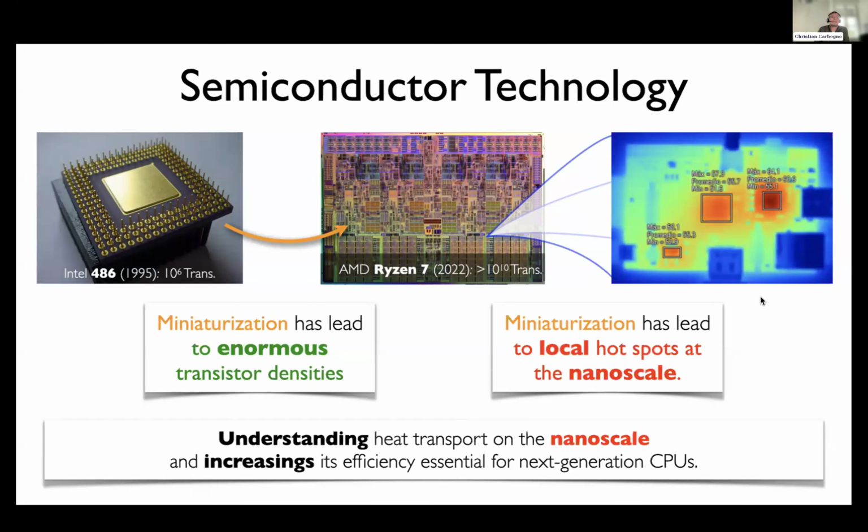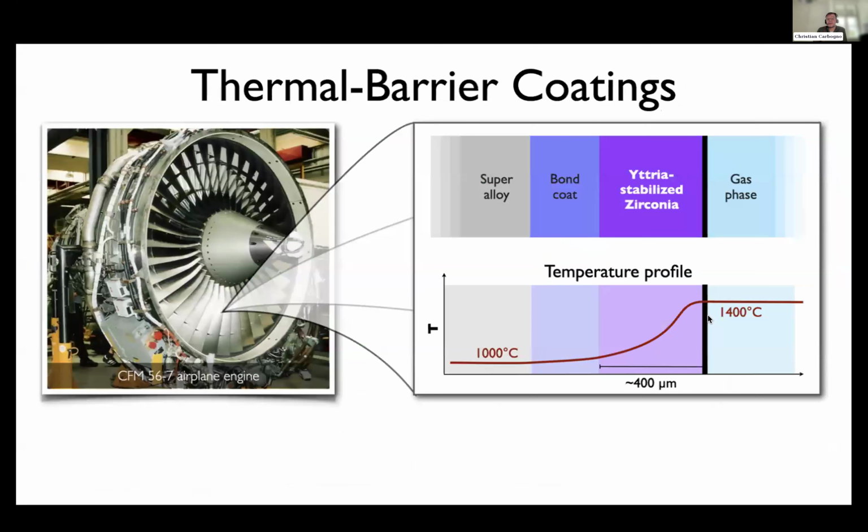So here, this is an example where we really have to increase lattice thermal conductivity in such materials. A converse example would be thermal barrier coatings, which are used in turbine technologies, for instance in airplane turbines. Here, a minute layer of ceramics, typically zirconia based, is placed on top of the superalloys that the blades are made of. And this extremely insulating material basically insulates away something like 500 K within half a millimeter, protects the underlying superalloy from the extreme temperatures generated during combustion.